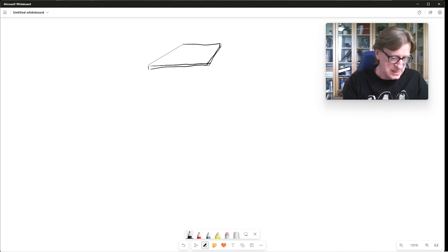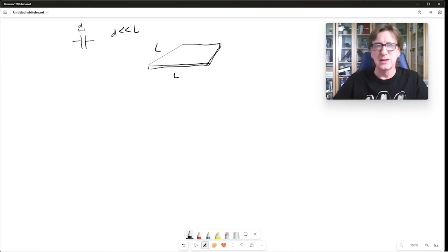And so in this case, let's say that, going back to my circuit here, if this is my capacitor, if this distance d, which is the farthest distance I'm going to get from the plate, if that distance d is much, much less than the length of one side, remember, it doesn't have to be the same, but L and L, as long as it's much, much less than the smaller length, then I don't make any detectable error by saying, okay, yeah, it's just infinitely thin from that.